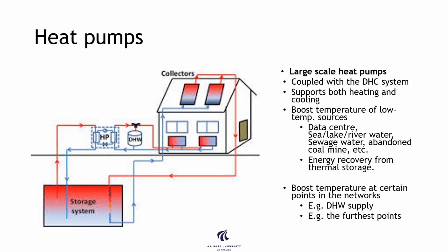And this is one of the advantages of using a heat pump in a district heating system, that now we can connect it to some bigger heat storage or heat source, compared to when we do it at your own household. Then there's a risk that you might only do an air to water or air to air heat pump, which is also completely fine, but it would be a little more electricity heavy over time, potentially, because we use an ambient source that can be colder than is possible to achieve in a district heating system.